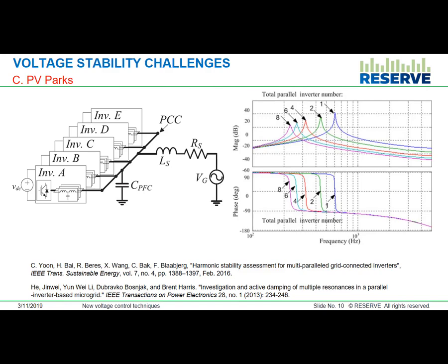typically, the control of every inverter is designed with some, let's say, thumb rule, where I design my inverter's control bandwidth to be roughly 1/10 of the resonance, because this is where the filter is active. So I would design my controller to be active until maybe this region. And now suddenly, because of the presence of inverters and the combination of grid impedance, if the resonance shifts, then it's within the control bandwidth, so the inverter would start reacting. This is the process called harmonic instability. So therefore, impedance measurement is very important.